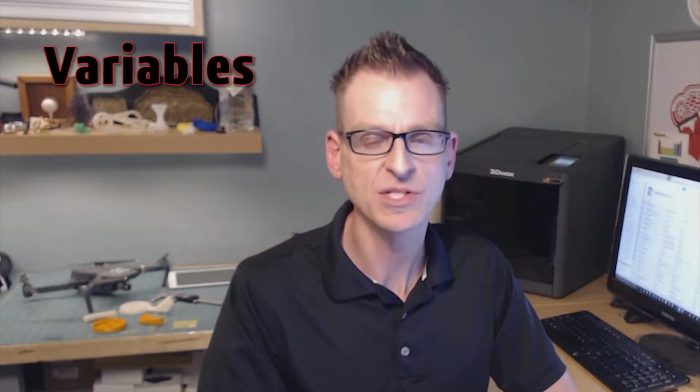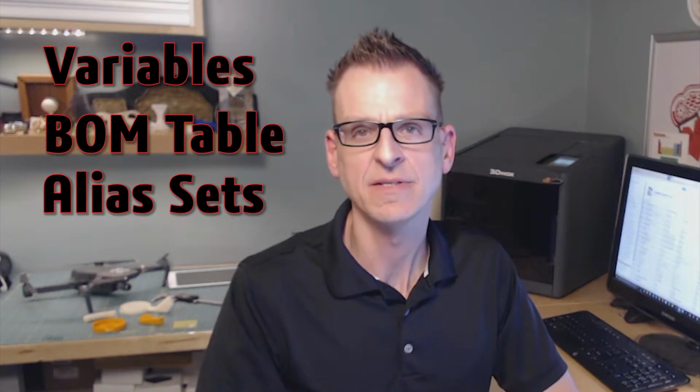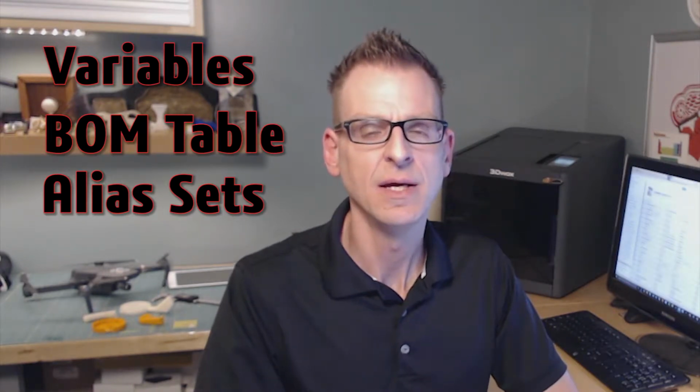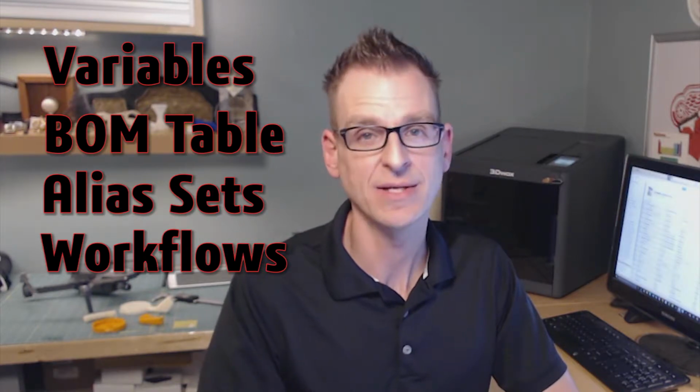As a PDM administrator, you need the proper permissions to set this up, but you also want to be familiar with the variables in your system, how to create a bill of materials table, even alias sets if it's applicable to your other business systems. And it's all triggered by workflows, so you want to be familiar with how to set up states and transitions as well. So let me go ahead and show you how to get this set up.